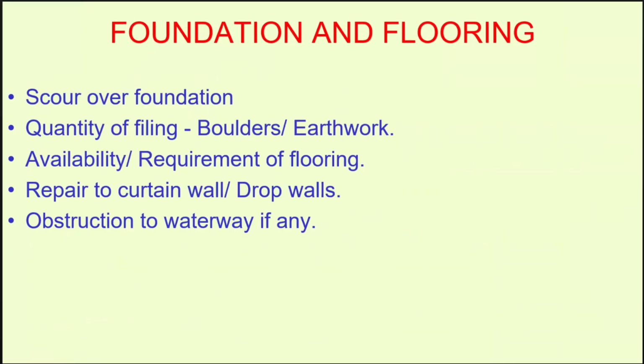Discover over the foundation the quantity of filling boulders, the filling of the boulders or the earthwork, and the availability and requirement of the flooring. You need a floor there to channelize the water and make it run faster so that deposition does not take place. But if the approach is already silted, then the water will stagnate and will not function properly. So you need to clean it and reset the flooring system. Whatever action is to be taken, that needs to be taken.